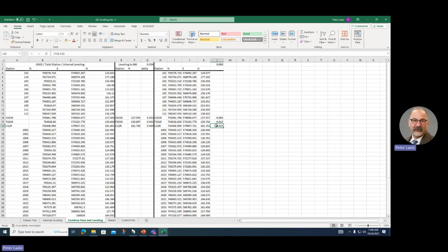I got 2 cores that agree within a few hundredths, and then if I add that one, now all my elevations are different by a tenth than if I don't hold that one. And I'm going to level through it anyway. Holding the elevation on the cores actually does change the horizontal, but in the 4th decimal place. So my argument is I'm going to level these anyway. What you're asking me to do is inconsequential.